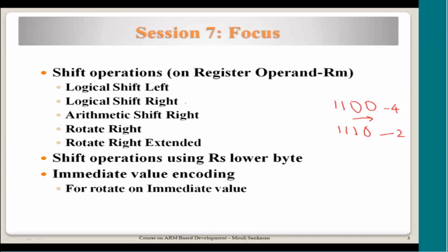What is logical shift right? If you do a logical shift right, this will become 0 1 1 0. So you are not preserving the sign bit. This is called logical shift right, whereas the other shift is called arithmetic shift right.